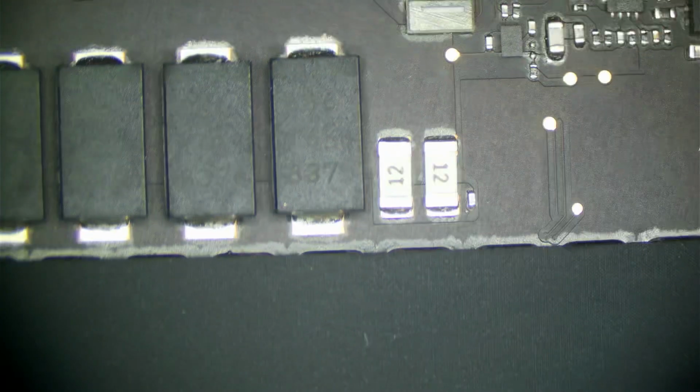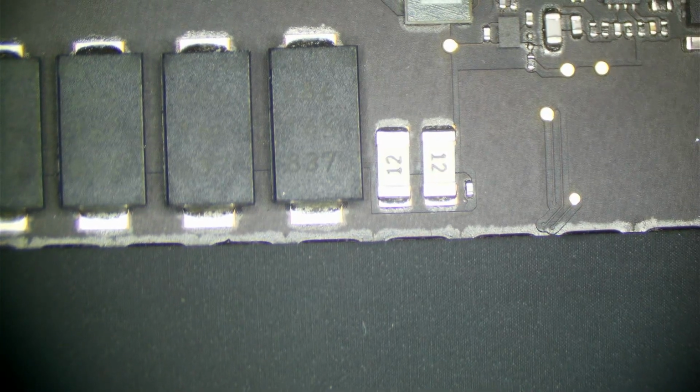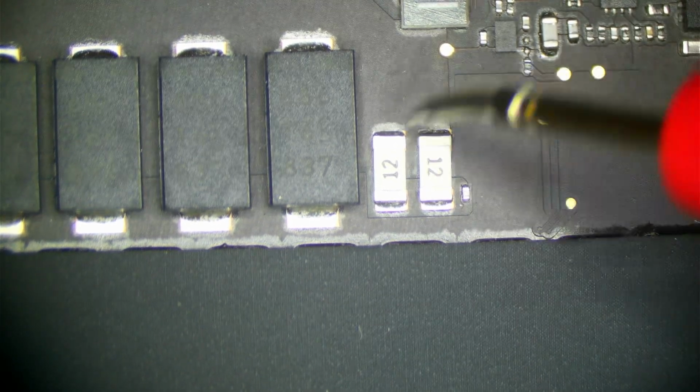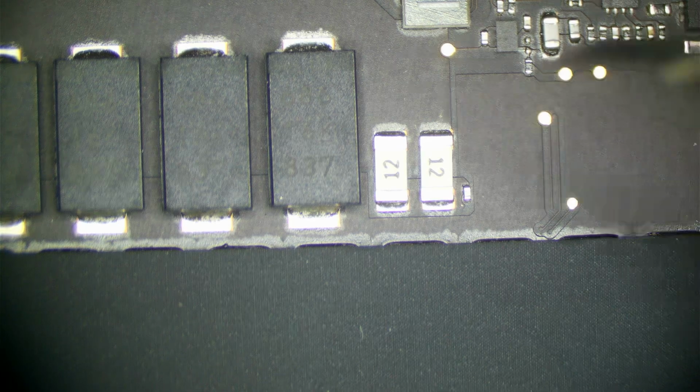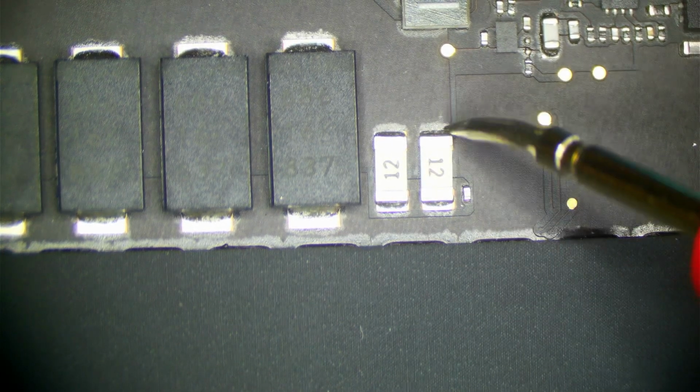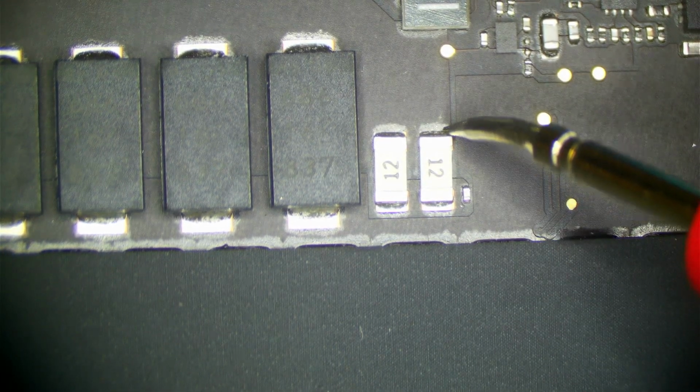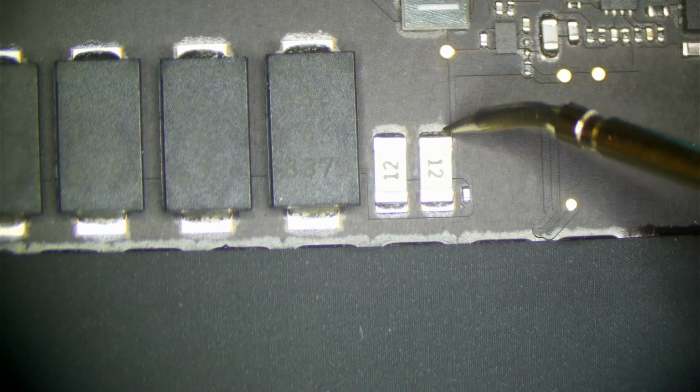So carrying on, I want to check what PP-bus G3 hot voltage is. And there's a few things that PP-bus G3 hot will tell us on a T2 machine. So if I have 12.6 volts, BridgeOS is pretty much loaded, and that means our T2 chip is mostly working. Now there's some very remote scenarios where you can be at 12.6 and have an issue there still, but 12.6 gives us a good idea that our T2 is working at least in some fashion, and it is at